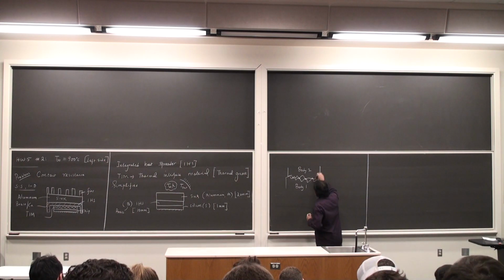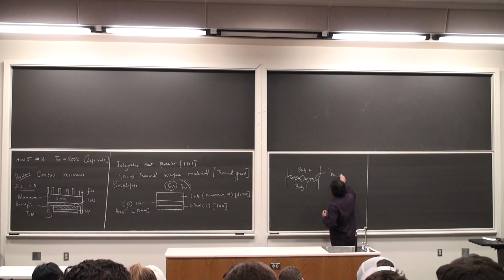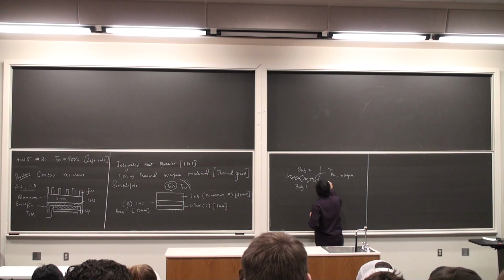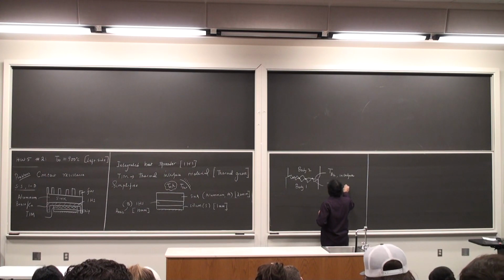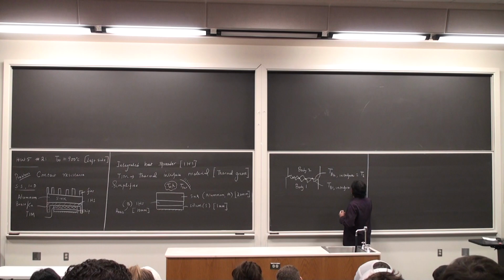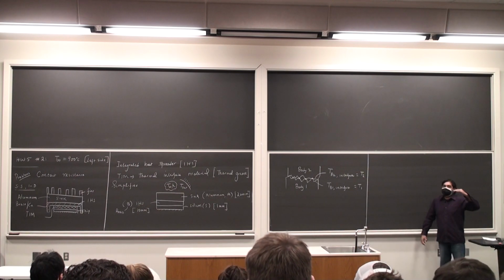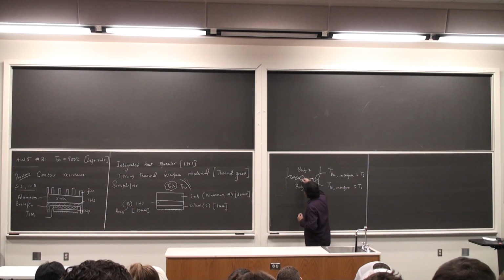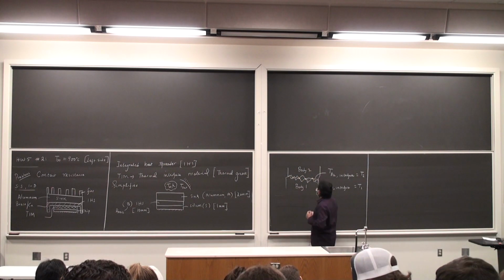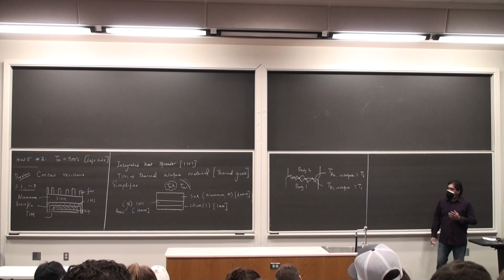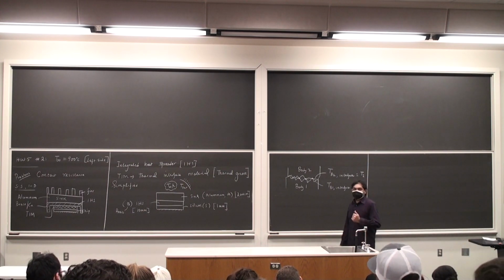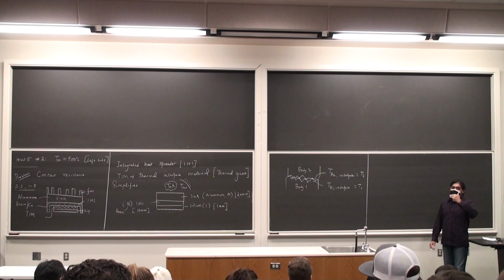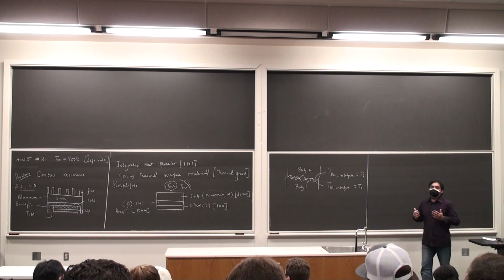Okay? So this will tell me that the temperature of body 2 at the interface is not the same as the temperature of body 1 at the interface. I'm going to call it T2, this is T1. These are temperatures at the interface. The interface is infinitesimally thin, right, in some sense, and you see that there is air gap here. And air is a very poor conductor of heat. So because of this particular reason, there is going to be a temperature gradient between body 1 and body 2 at the interface, and if you would like to model this as a thermal resistance, here is an option.